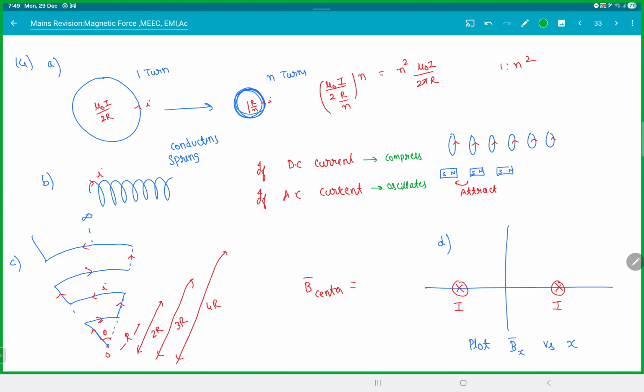Remember I told you how to catch snakes with this. This is actually what happens inside a transformer. If you remember, in a transformer we have these coils like this, the primary coil and the secondary coil with a lot of turns. So when you're sending a current there, the coils actually oscillate. Whenever the current is going in and out, the coils are oscillating continuously. So if you go near a transformer, you'll hear a buzz. There's a sound like this when you're close to a transformer. I don't know if you ever heard it. Nowadays the transformers are quite hidden. Previously, they used to be on the road, so you could actually hear it when you're walking beside. That oscillation is actually because of this coil's oscillation. And this frequency is around 50 hertz.